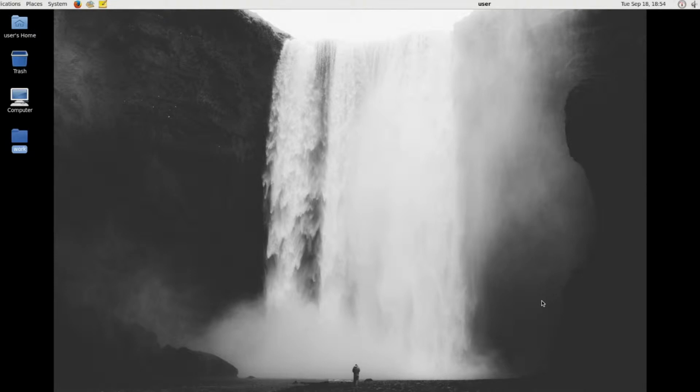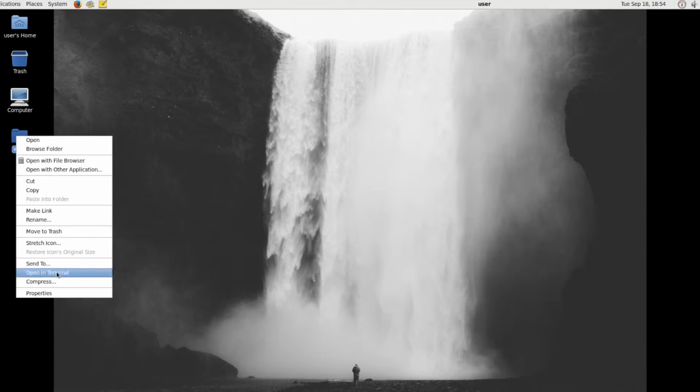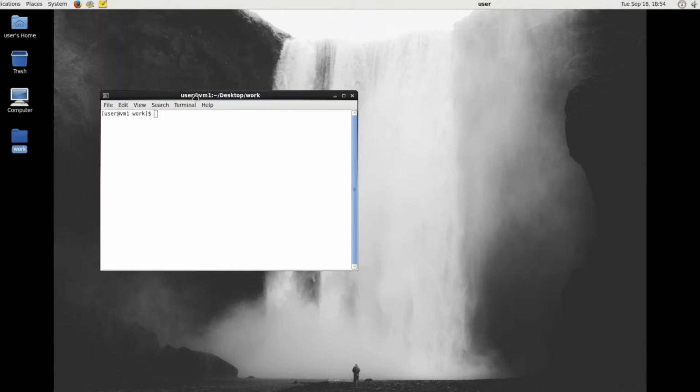First of all, we need to choose a directory to work under, or the directory that you invoke Custom Compiler. Here, we choose the folder work. To open it up, right-click, open in Terminal. Let's take a look at what is inside this directory. You can type in ls.